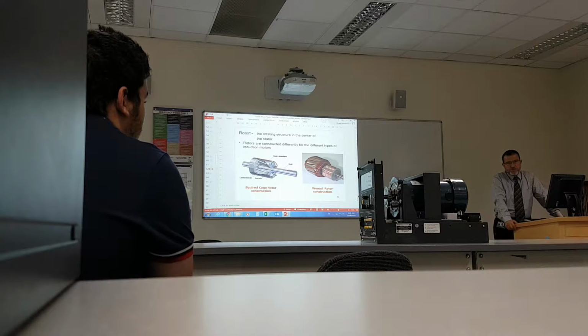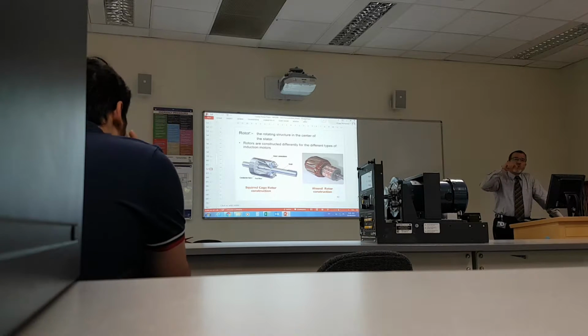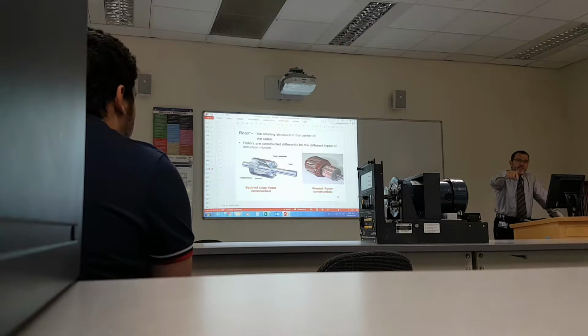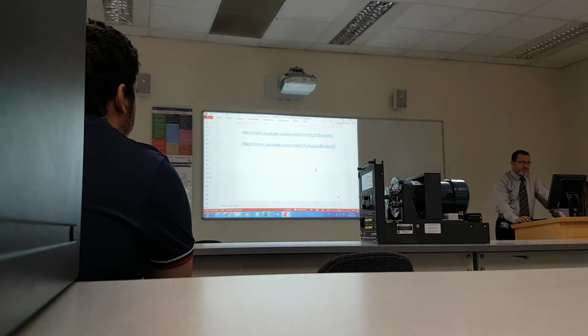But in the wound rotor, it's an induced current. It's not even a field current. When you say a field current, it's something that we are supplying directly. This is current induced from the rotating magnetic field of the stator. There's no current that we're supplying to the rotor whatsoever, even though there are slip rings. Don't let the slip rings fool you.